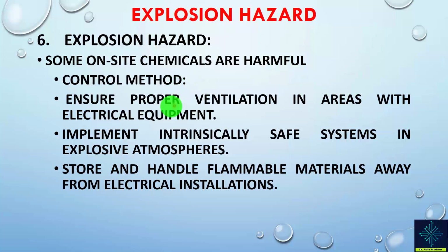charges. Some of the control procedures would be to ensure proper ventilation in the areas with electrical equipment, implement intrinsically safe systems in explosive atmospheres, and store and handle flammable materials away from electrical installations. Also, good grounding systems would be helpful and required to control the explosion hazards.